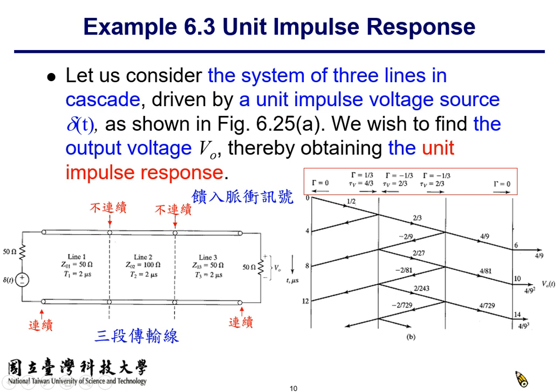But if you look into the left, that would be 50 minus 100 over 150, that would be minus 1/3. If you mess up this order, you will end up with a wrong sign. So on this boundary, the reflection coefficient would be 1/3, and tau equals 4/3. On the other hand, if you look from right to left, the reflection coefficient is minus 1/3, and the transmission coefficient is